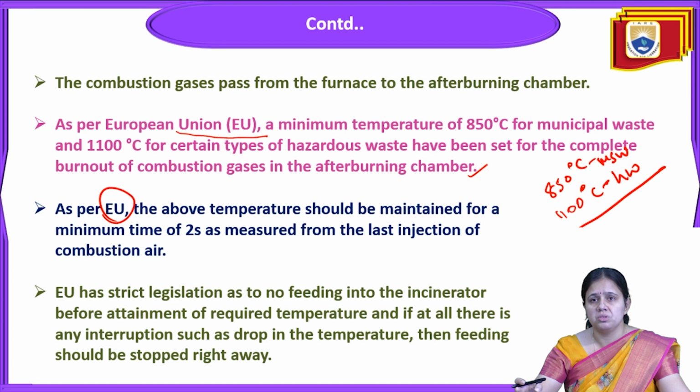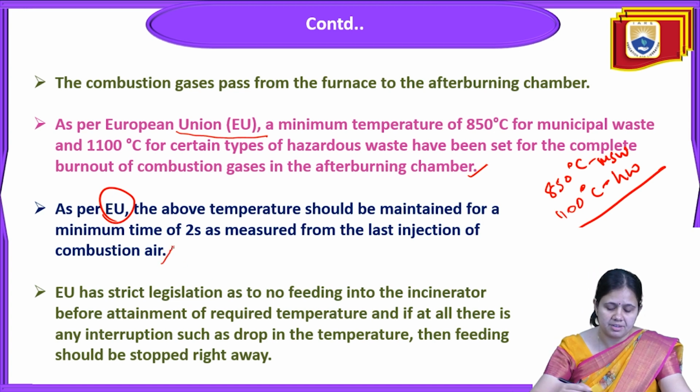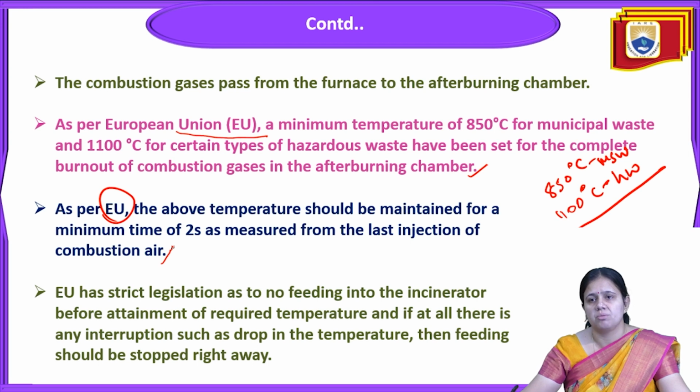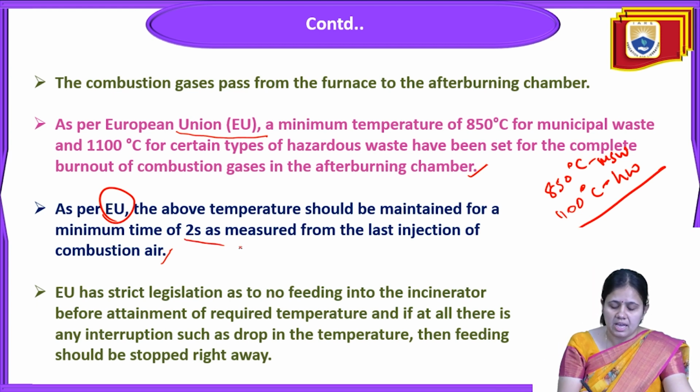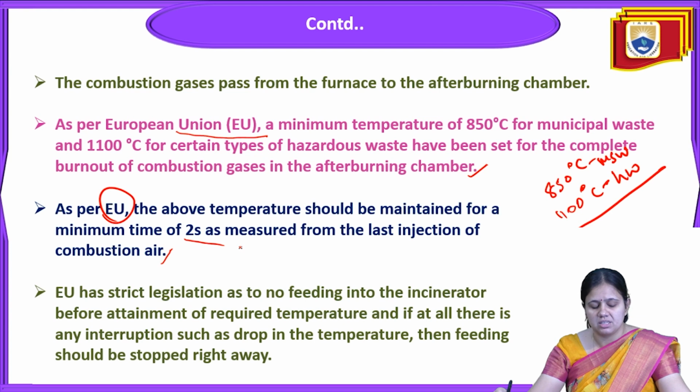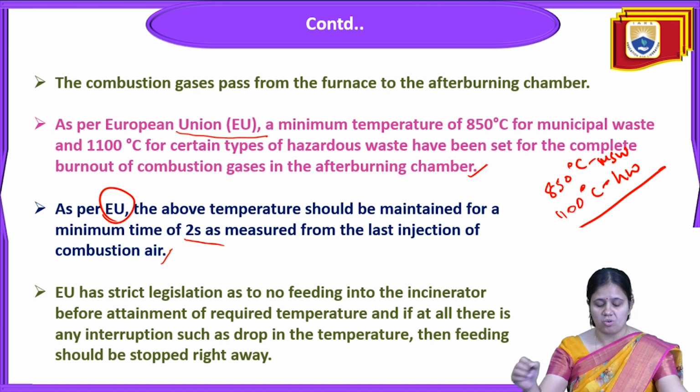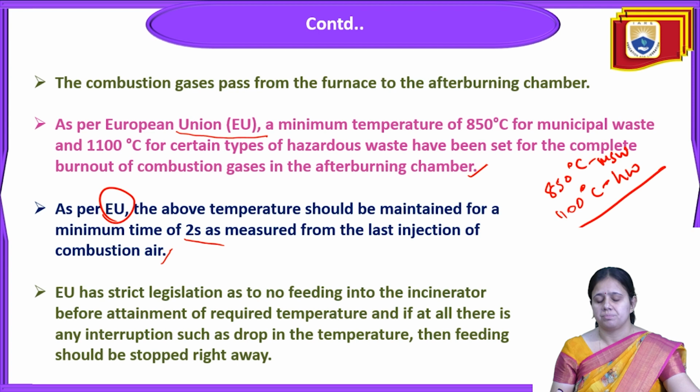As per the EU, the above temperature should be maintained for a minimum time of 2 seconds, as measured from the last injection of combustion air. The European Union has strict legislation of no feeding into the incinerator before attainment of the required temperature.